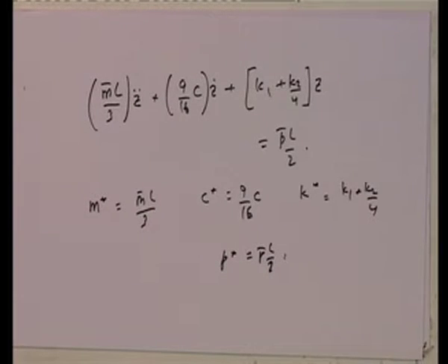Okay. Let us look at this. This is the beauty of the principle of virtual displacement. The beauty of the principle of virtual displacement is when you use theta as the degree of freedom, the stars that you get are all given: the m star is a mass moment of inertia, k star is a rotational spring constant and p star is a moment.